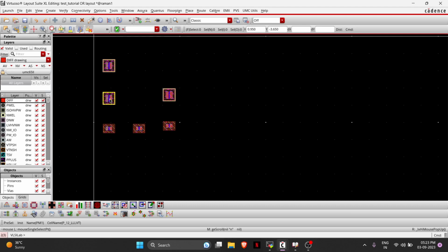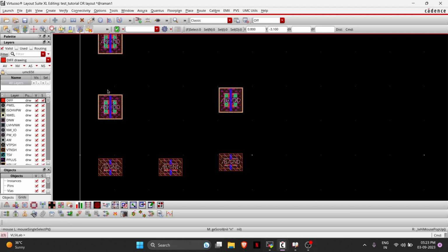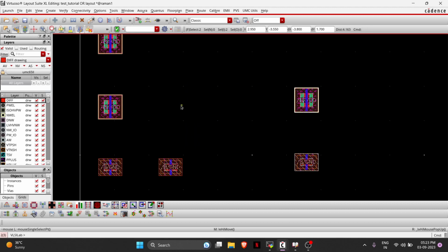After that, identify the transistors. This is PM0, this is PM1. So these are two PMOS connected in series. This is NM0, NM1. So these are bottom transistors connected in parallel. And these two transistors are inverted. So we can just do it then for now.